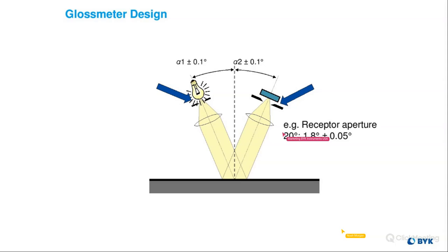Typically, we find that a black felt is the best type of material for that, because of all its microtexture. It doesn't reflect any light. Where you can get that, off the top of my head, I don't know. But you could reach out to one of us and we could look at some options for you. We also recommend doing a Google search of where to get black felt. But I think that is one of the best materials for this type of measurement, especially for transparent materials.